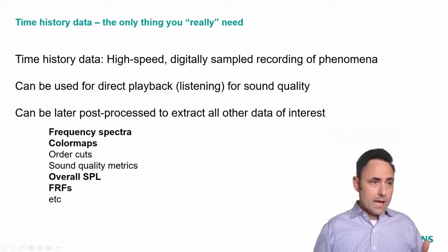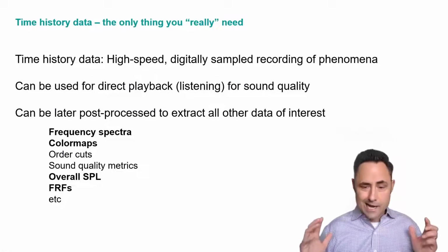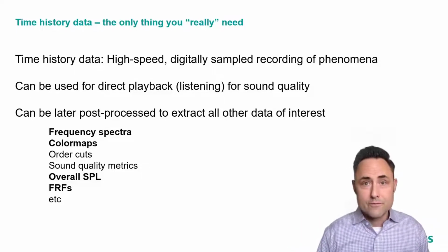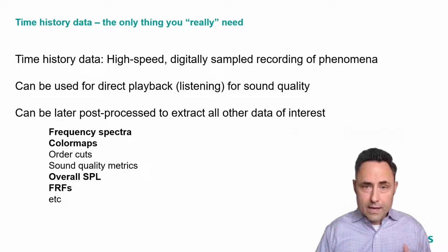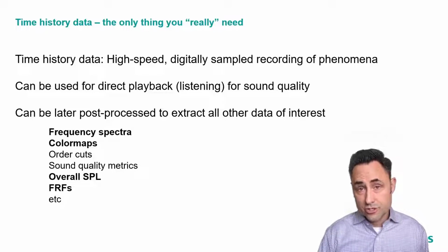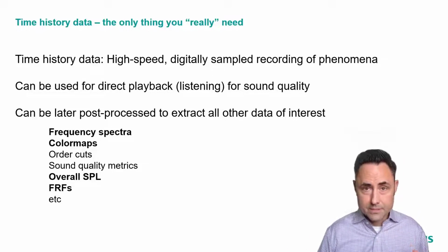Okay, and what is time data, or throughput data we sometimes call it? It's high-speed, digitally sampled data. It's a tape recording, if you will, of everything that those transducers, the microphones, the accelerometers, the strain gauges, everything those transducers are seeing gets digitized, and it's a recording of everything that happens.